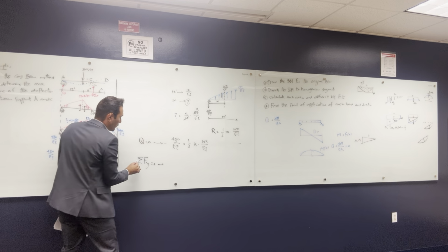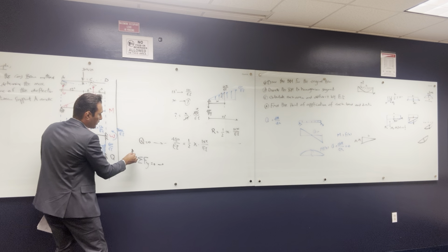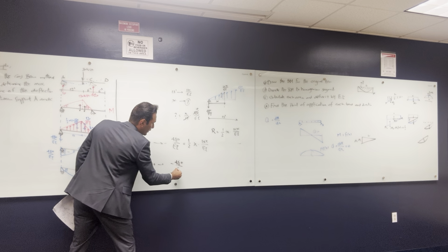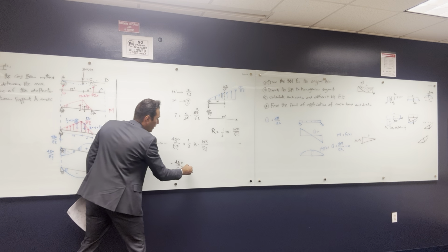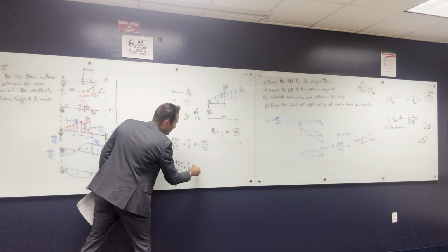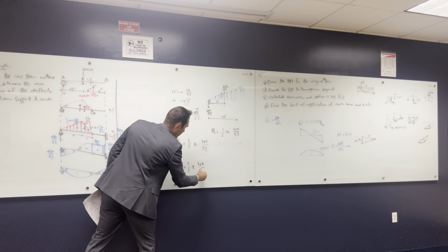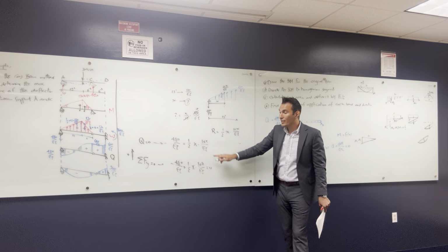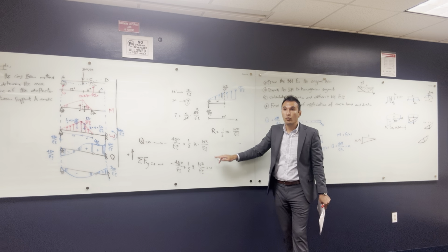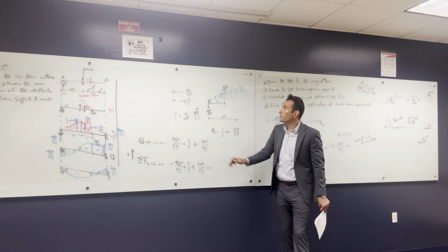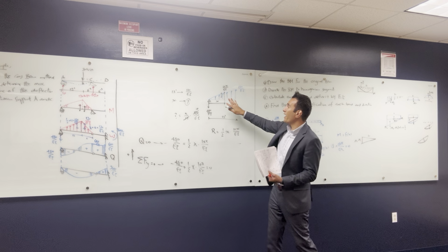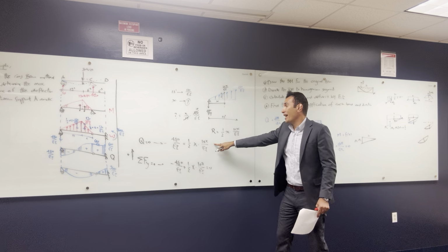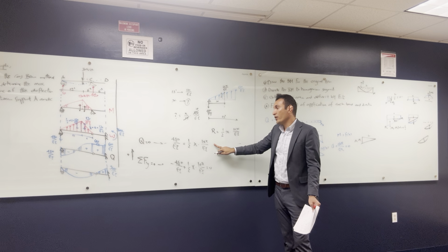That's the same way if you want to have the shear equal to 0. So you are saying that up is positive. So you are going to have this as negative 480 over EI plus 1 over 2X multiplied by 10X over EI, and all this is equal to 0. Then you can bring this to the other side, it's going to give you the same equation. So both are okay, all right? So what I want is the amount of load to be equal to the amount of shear. So this is a second degree equation. You can solve this equation.